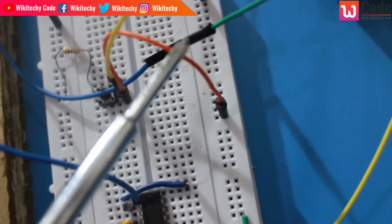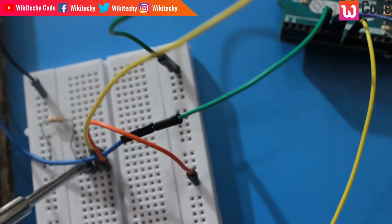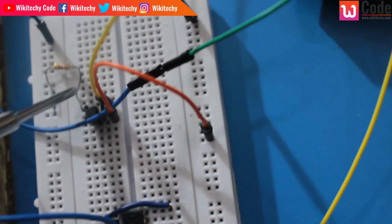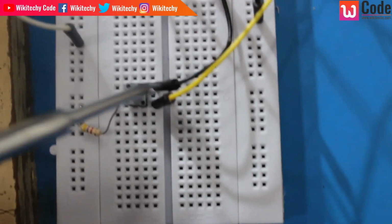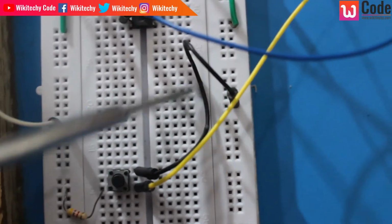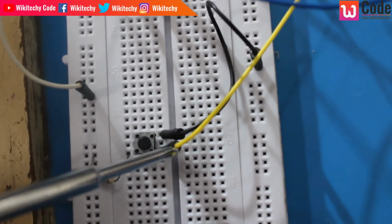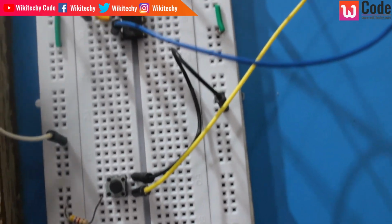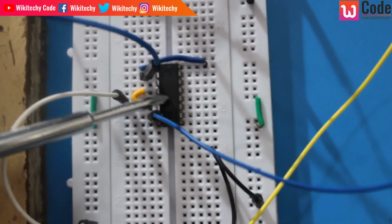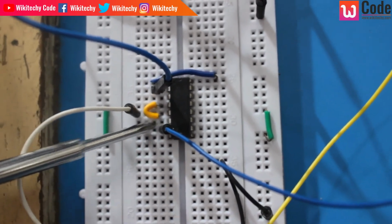So one end of the push button is given 5 volts, the other end is connected to the Arduino. The opposite part is grounded. Similarly, over here the push button got 5 volts from here to here, and the other end is connected to the Arduino, the other end is grounded. So this is how we connected. So this L293D IC got the inputs ready. Now I need to get the outputs.